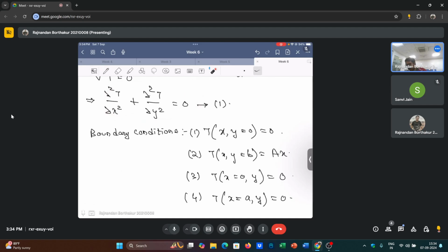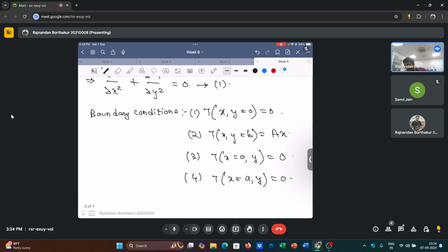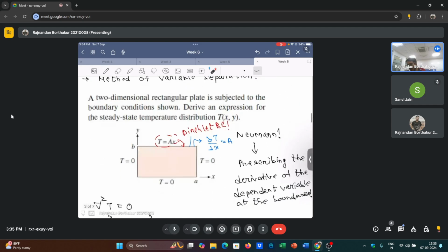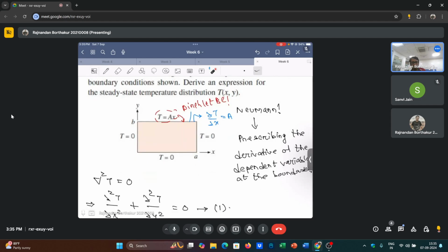Okay. So let's name this as equation 1a, maybe this is 1b, this is 1c, and 1d. All right. So now, as I have said, we will use something which is known as the method of separation of variable. This is possible because, at least in one direction, your boundary conditions are also homogeneous. For instance, if I pick the x direction, on this face, the boundary condition is homogeneous, meaning that your temperature is 0 there.